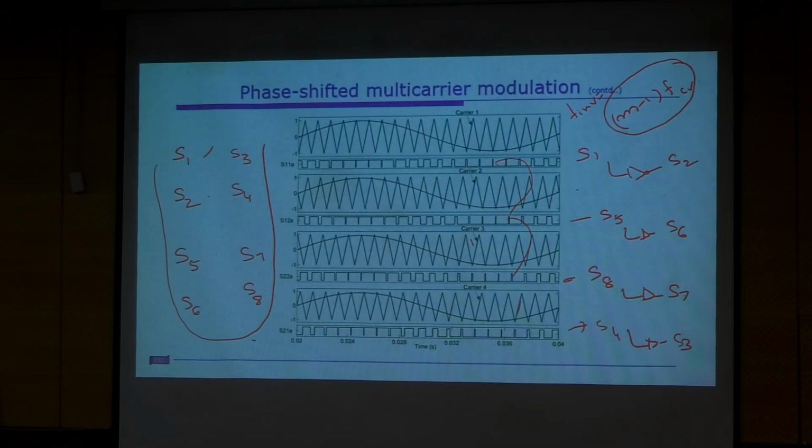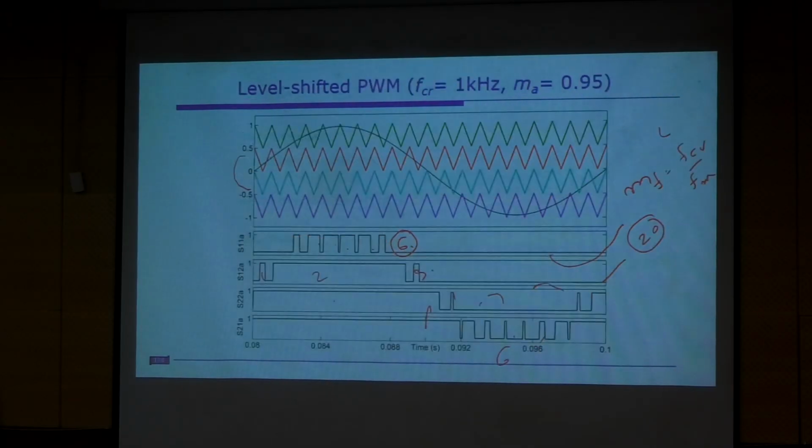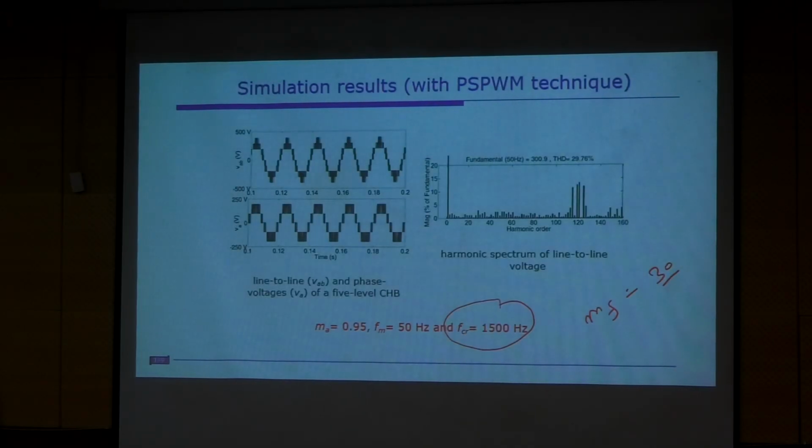So in case of a 5-level inverter, it is m minus 1, that is 4. In our case, our MF is 30, so that means 4 into 30, which is 120. Based on that, you have sideband harmonics, which appear at this cluster, 120, 240. Understood? Clear?